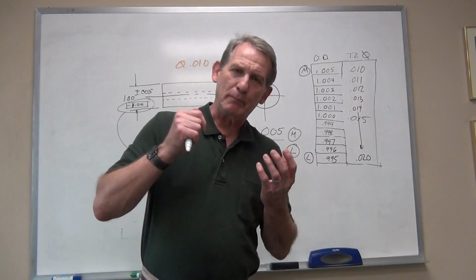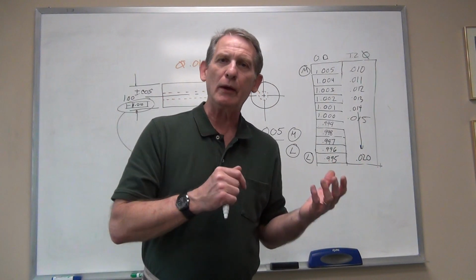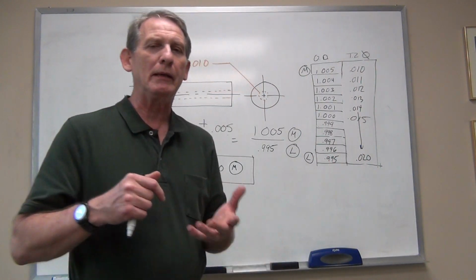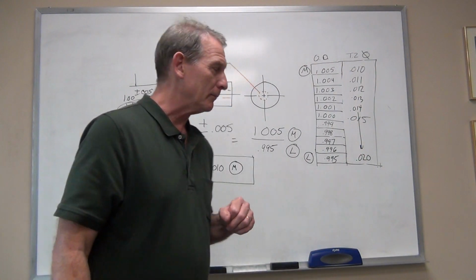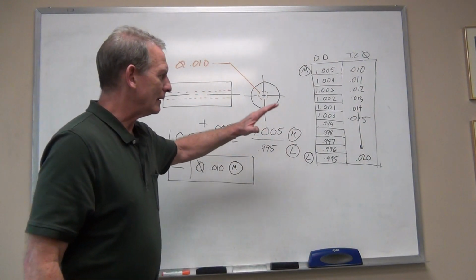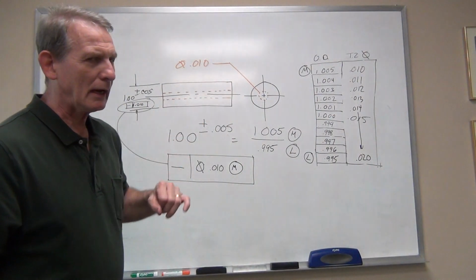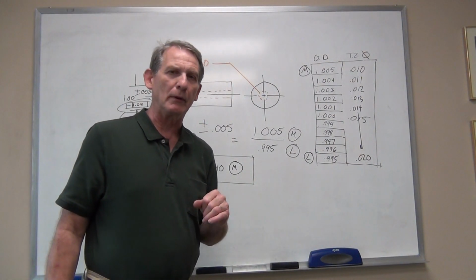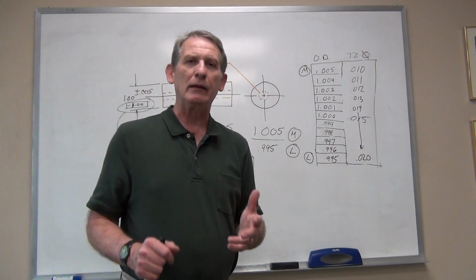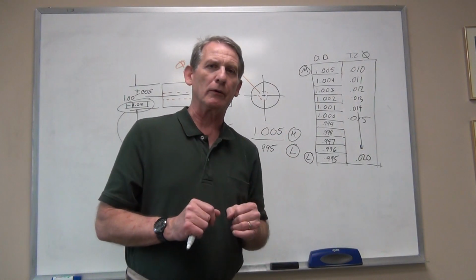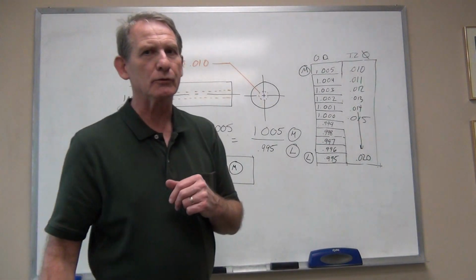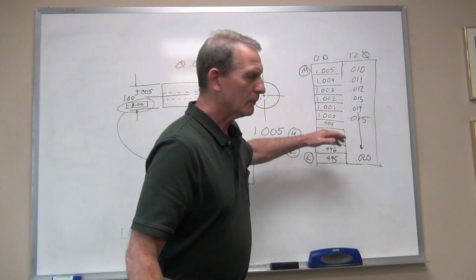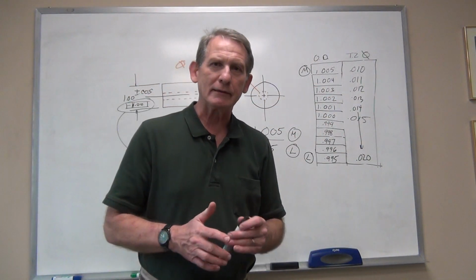That allows that bent shaft to go in. It just opens up the hole a little bit, and the bent nature of the pin doesn't matter at that point. So this is the bonus tolerance that you're going to hear talking about, but in order to evaluate it, you have to measure that actual part. If you've got a basket of 100 of these, you have to measure 100 diameters, and each diameter is going to have its own size tolerance zone.